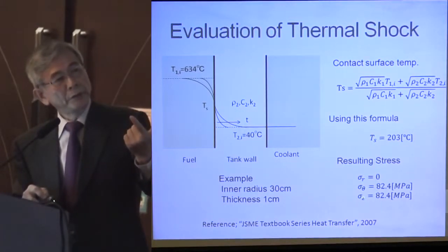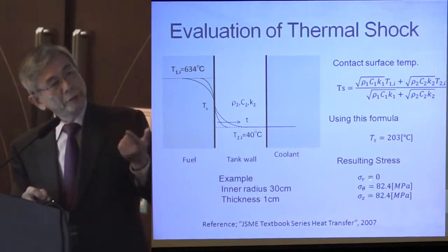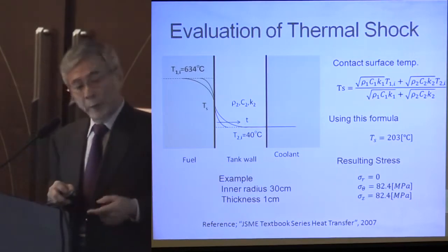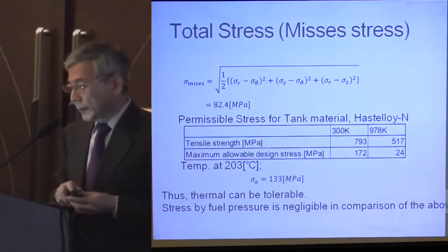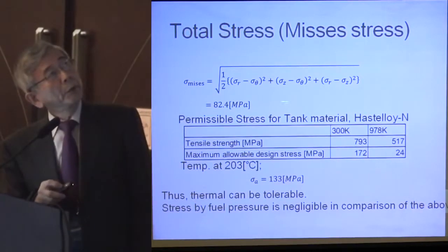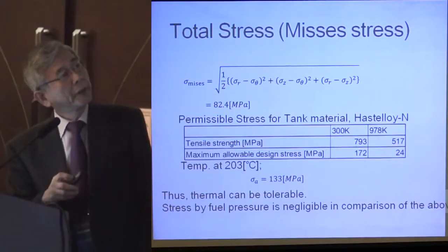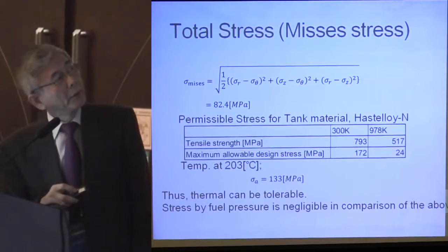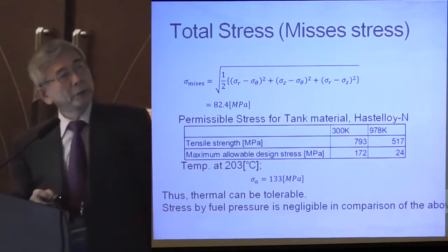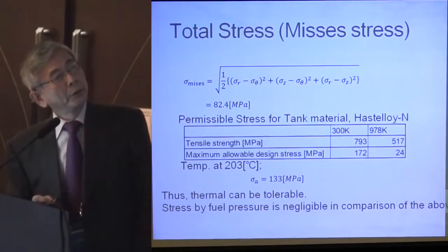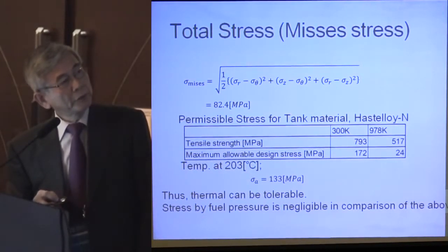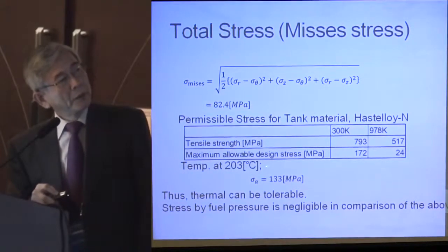The actual stress is about 82.4 megapascal. And we calculate total stress. It's 82.4, and the permissible stress of tank material of Hastelloy N, where we interpolate at this temperature, the permissible design stress is 133 megapascal.